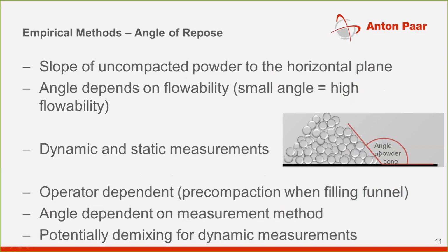What is the case here as well is that this is quite operator dependent. The sample can be, again, pre-compacted when filling the funnel, for example, if it's led to flow out of a funnel, which will then have some preload on the powder. It might actually fluidize, it might demix, and there are a lot of different methods, so the angle actually depends quite strongly on the measurement method.